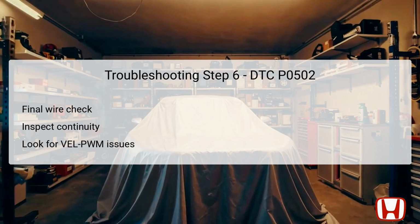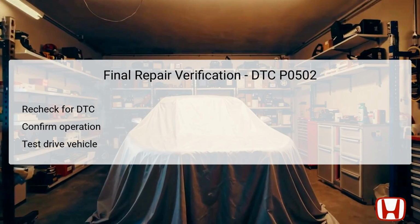If continuity fails the test, repairs will need to be made to the VEL PWM line to restore proper function and communication between the sensor and TCM. After completing the necessary repairs, it's imperative to verify that the issue has been resolved. Reconnect all components and clear any existing DTCs using the HDS tool. Perform a test drive to ensure that the vehicle operates without interruption and that the warning light does not reappear.